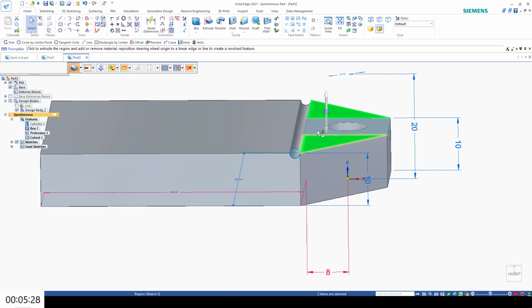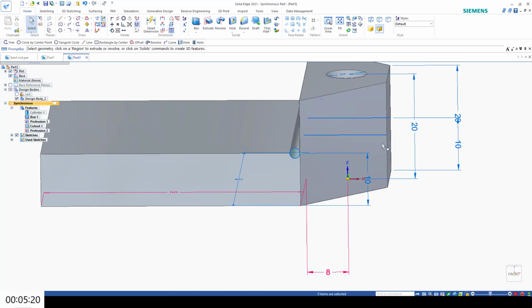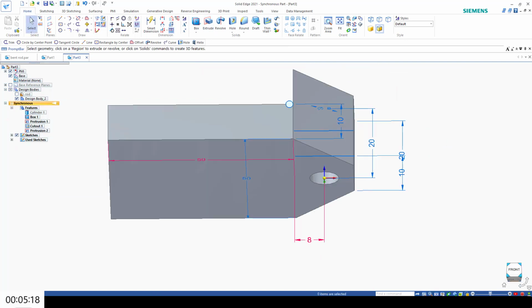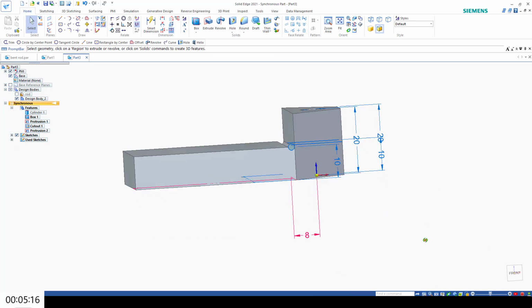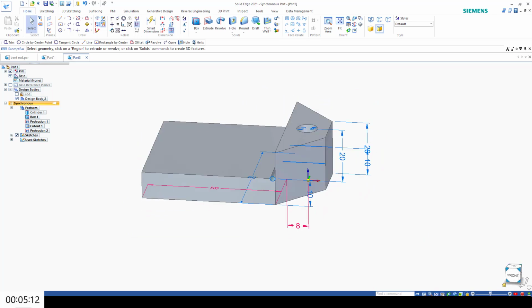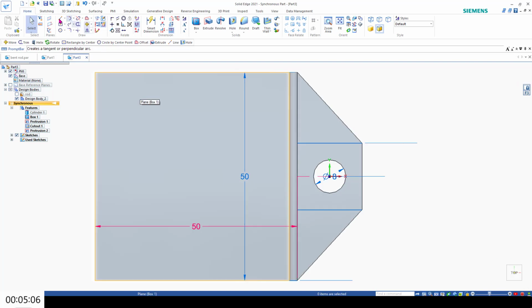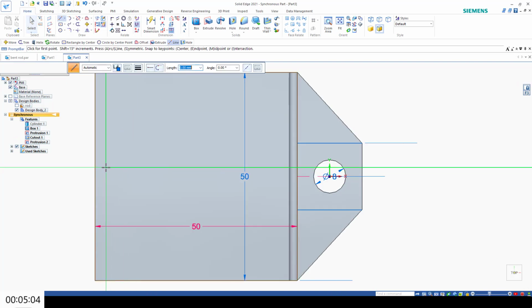The other thing I'm going to do here is grab those faces that I did before, and I'm going to go up 10 millimeters. The reason I want to do this is because I want a face to touch the side of the table edge or shelf edge that I'm going to rest this on. In the past with this lamp bracket, I've always had a problem that it spins. All of a sudden I'll be working along and it'll have twisted out of place and the lamp falls on me. It's actually pretty funny. So that's why that's there.